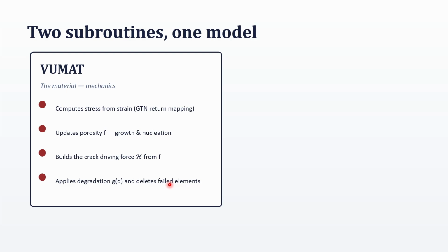Essentially we have to use element deletion in these kinds of simulations. Why? Because whenever your F reaches Ff, the stress carrying capacity of that particular element becomes huge.